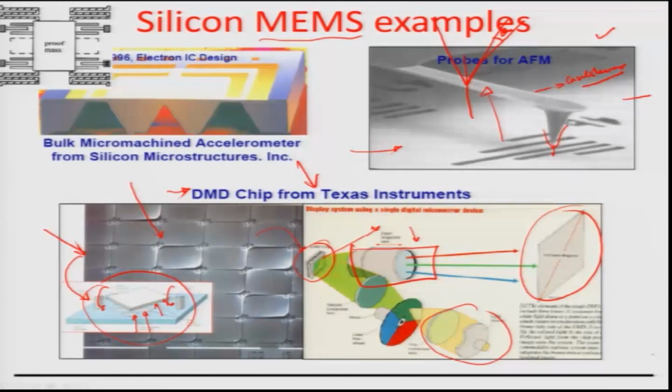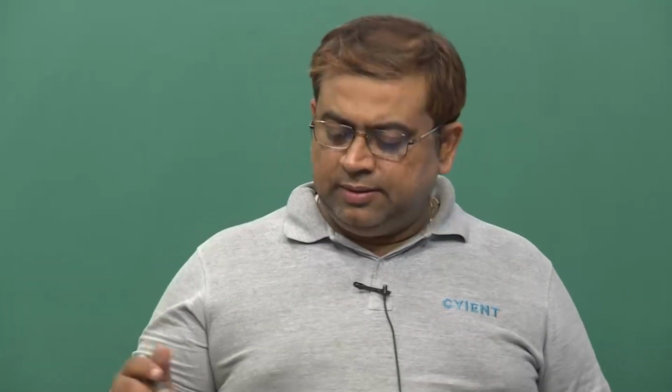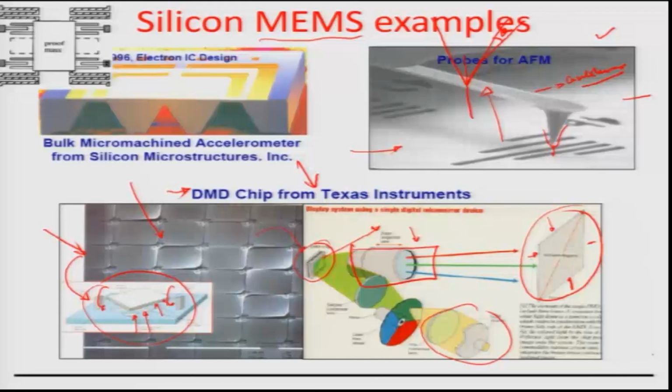The small micron by micron dot which is otherwise formed by reflected light in this focus, and is now away from the focus, comes as a dark pixel. And so, there are series of dark and bright pixels which could make an image, and such an image could then be projected onto a projector screen. Okay. And this can be one of the very fantastic examples of how you can digitize an image with respect to electrical signals.